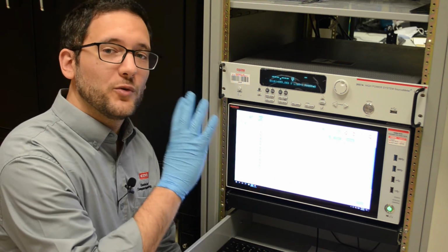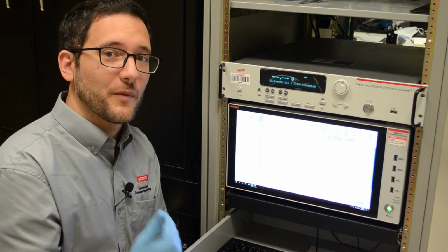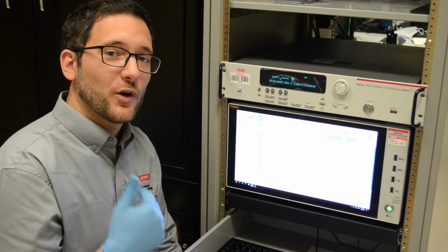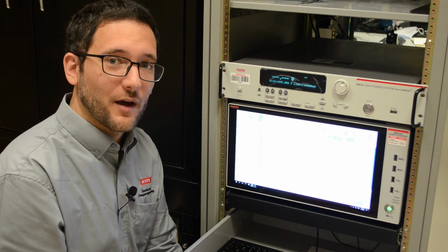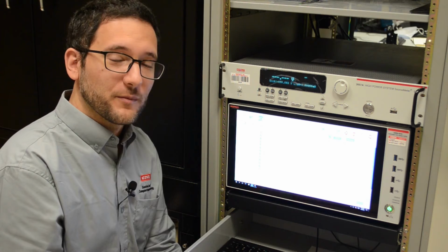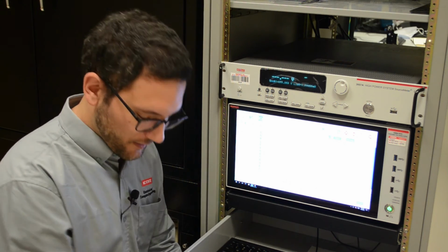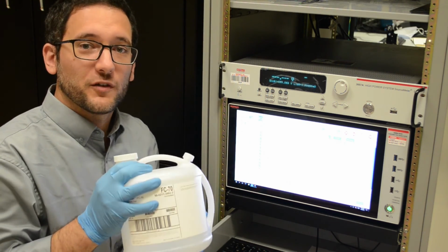In addition to using the right kind of measurement equipment, we also have to go back to think about the measurement setup itself. As you go to higher and higher voltages, you risk the air around the device breaking down, which would actually increase the current before the device breaks down. To combat this, we can use a liquid to protect the device.